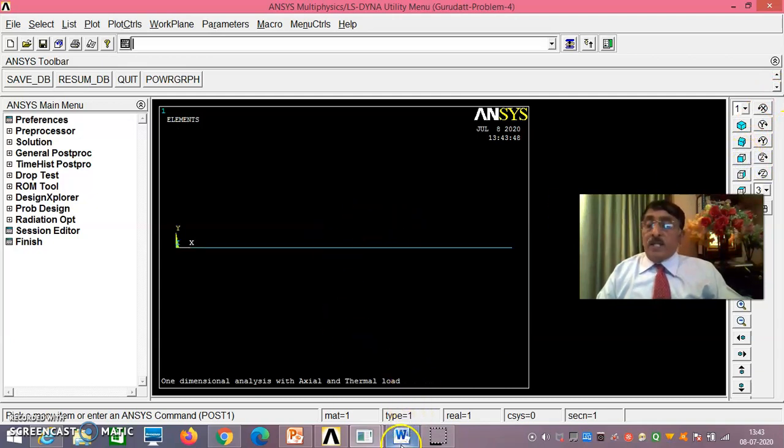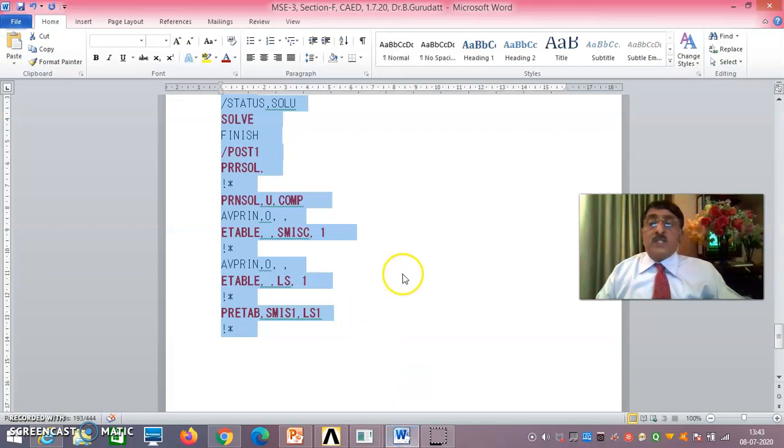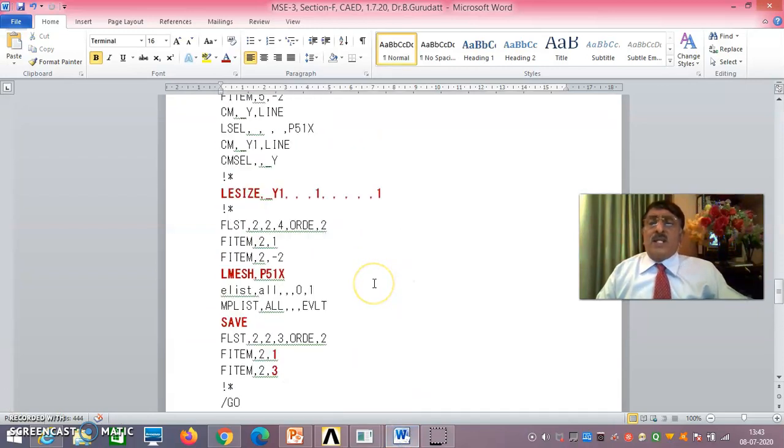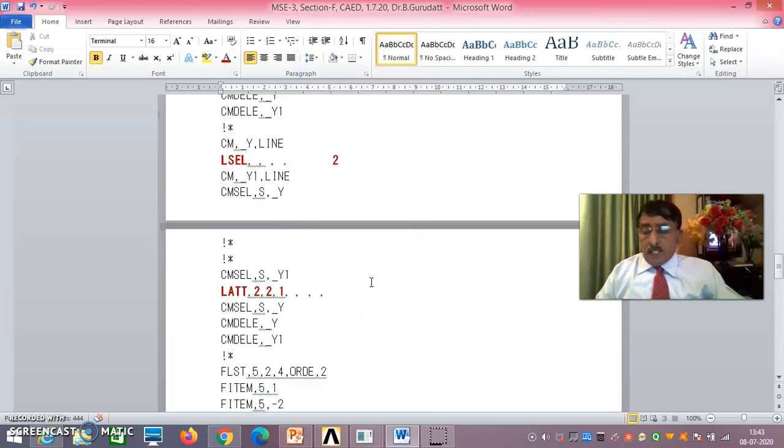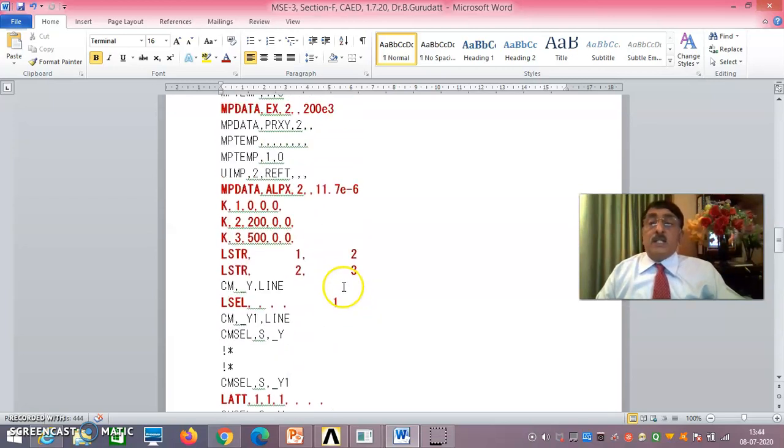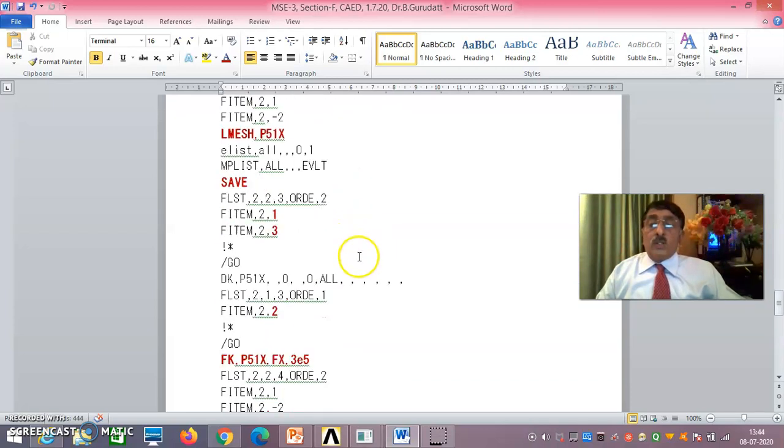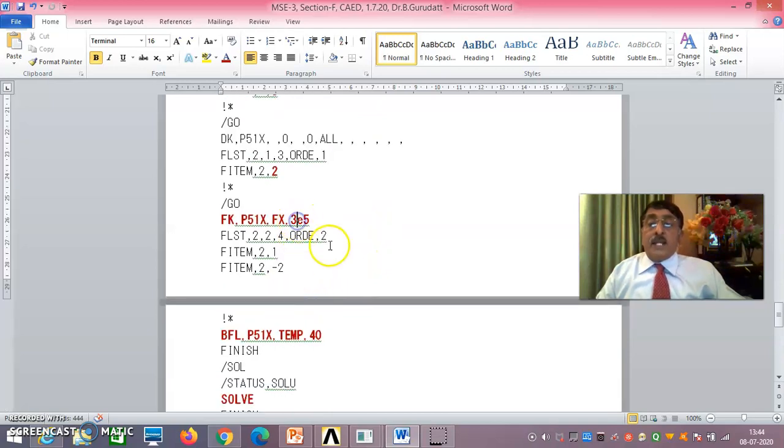Now you see here, the advantage of this is, I'm just telling you, you can change anything here. Whatever I marked red, you can change anything. Earlier, 0.22030 was the displacement you had got. I had made the load 3E5. Let us say I'll make it 5E5. That means 3E5 means right now I have made 3 lakh newtons. I can change it to 5E5. When 5E5 is done, naturally the displacements should be more and the stresses should be more. All you can change here.